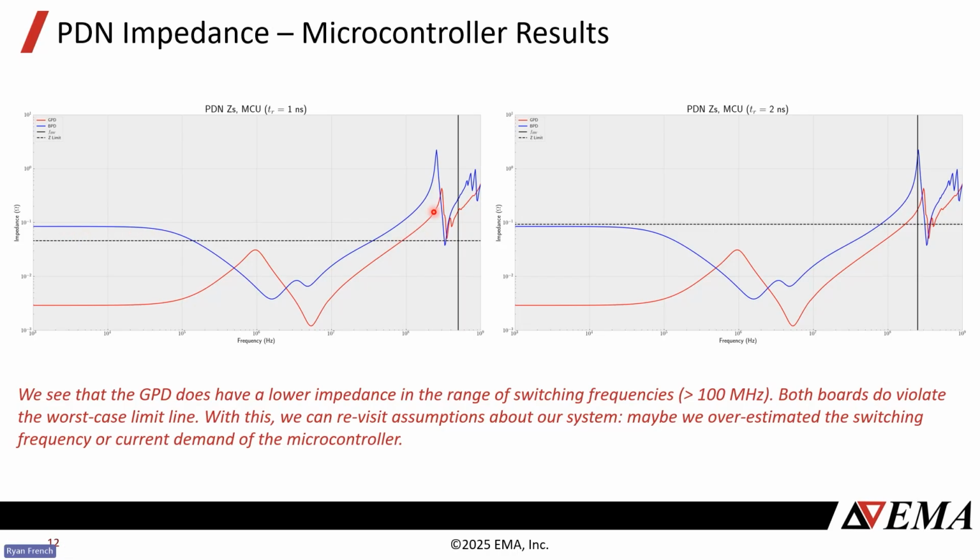And even up at the higher frequencies, this good design with the assumption of 1 nanosecond fails. Well, I'll keep harping on this, but even an experienced SI engineer following best practices, you may not pass. Without simulation, you may not know how your board is going to perform. And again, 2 nanosecond rise time gives us a little bit more margin, but we are still violating that limit.